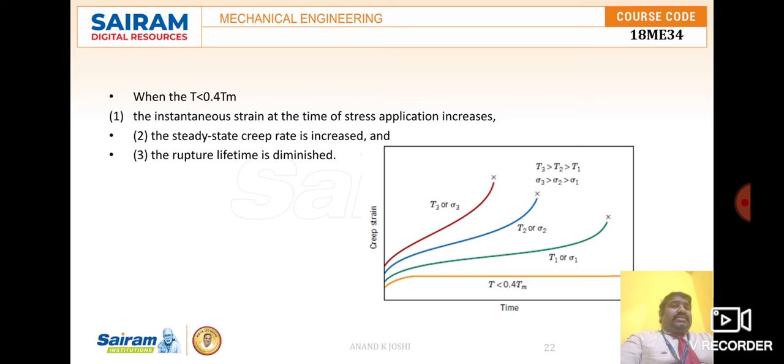With either increasing stress or temperature, the following things are to be noted. First, the instantaneous strain increases, as you see in the figure. That means the creep you observe here increases, and the steady state creep rate increases.